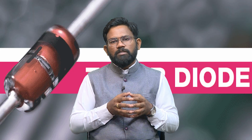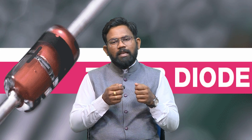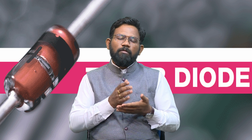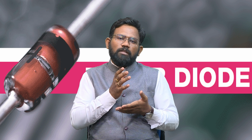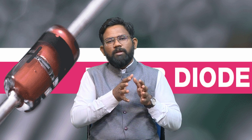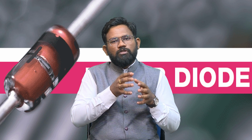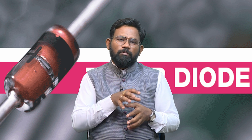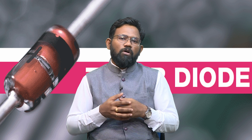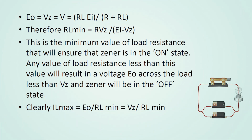We are studying the condition for RL minimum, so it again has a particular limit. The minimum value of RL should be such that it keeps the Zener in the on condition, and if the value goes below that, the Zener will come into the off state. So clearly from this we can find that the value of current IL max is equal to E naught divided by RL minimum, and it is equal to Vz upon RL minimum.